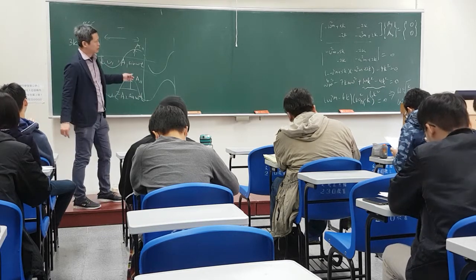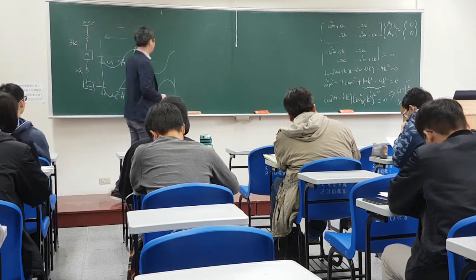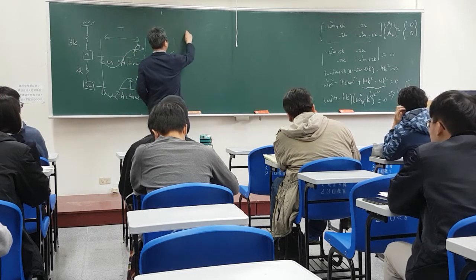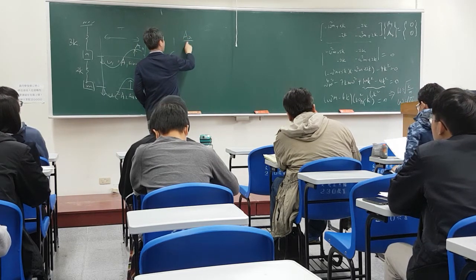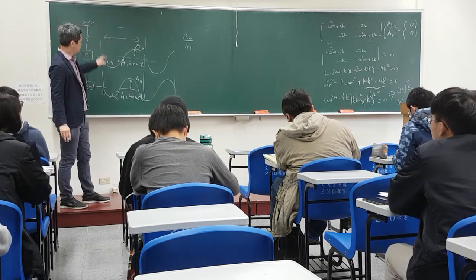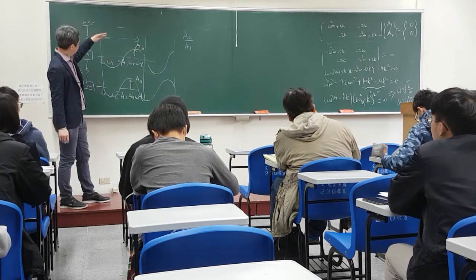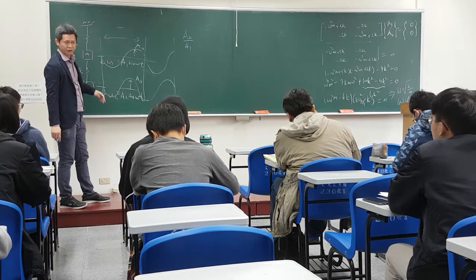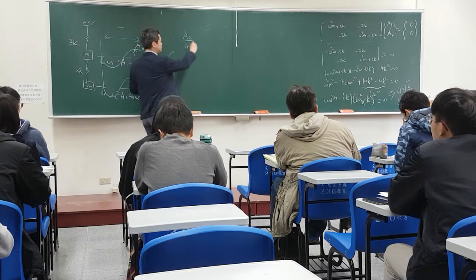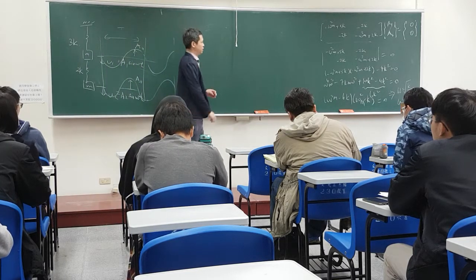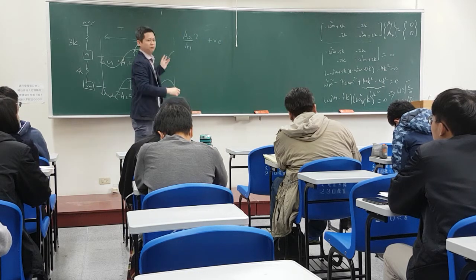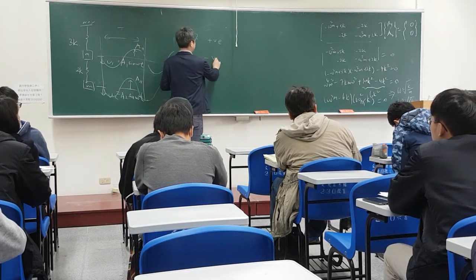So now what we're interested to find out is, will you be able to find what is the relative amplitude? Okay, A2 over A1. Because for vibrations, it could happen that you could move in phase. It could also happen that you move out of phase. How do you find this ratio? If they move in phase, this is a positive value. If they move out of phase, this is a negative value.